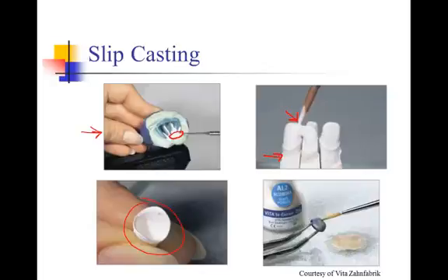So in the case of this product, a glass powder is made into another slurry, a very watery slurry, and painted onto the surface, and then melted, and capillary action, again, in this case, causes the melted glass to wick into all the unfilled pores and fill that empty space in. Unfortunately, in our test results, it seems that about 5% of the specimens do not have the glass penetrate entirely, and so there's some large porosity left in the middle of the product.